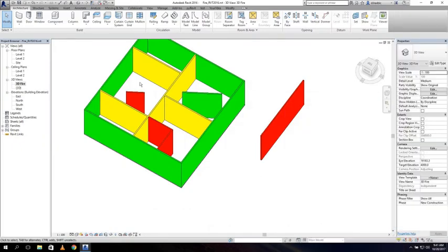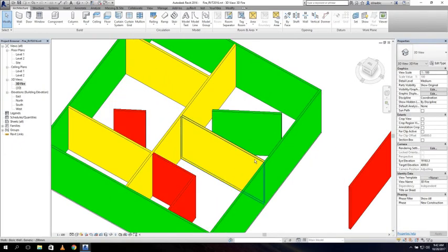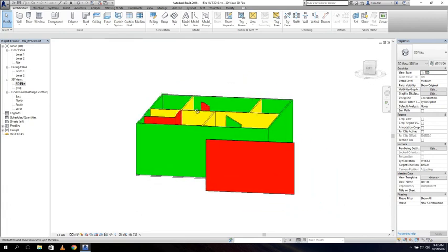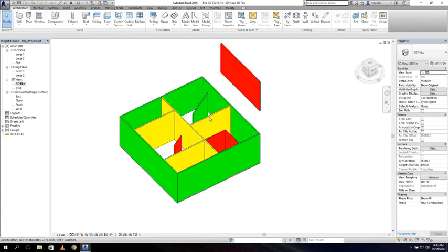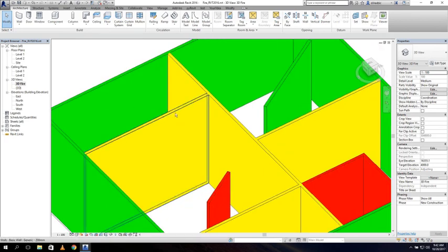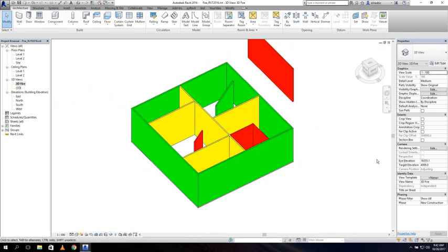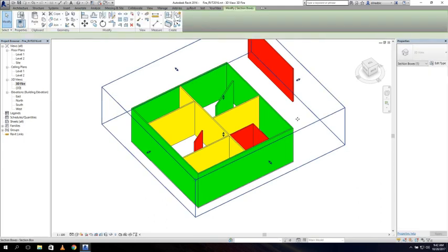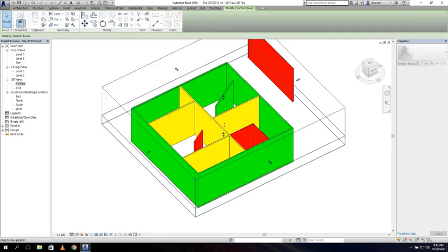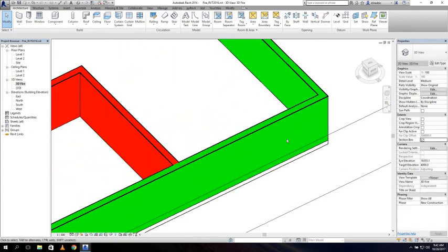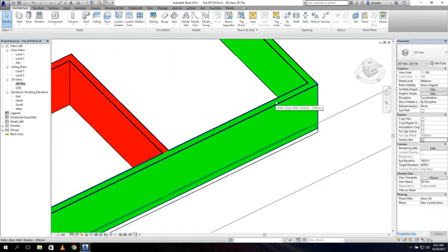And if I go back to our Revit file, as you can see, the result is, I think, better because it doesn't override the lines of the wall. And if I go to section box, if I put it on, I can just go lower, and you can see it also overrides the cut pattern and the cut color.